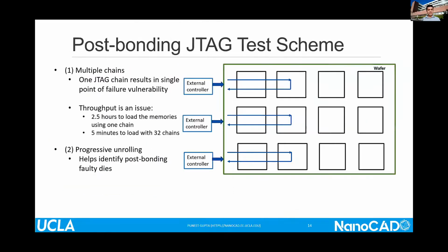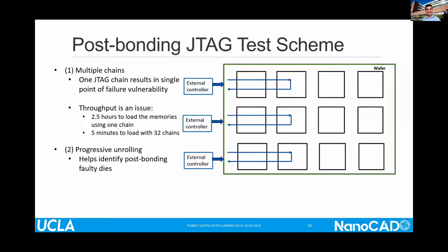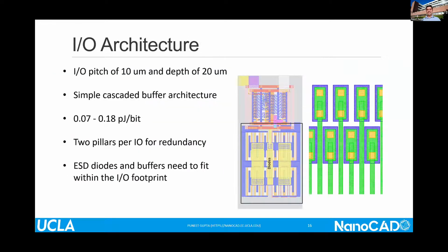So silicon, yes, the cost calculation in the beginning accounts for that, but it assumes that your IOs are of this style. The simpler IOs, these are not SerDes links and things like that. So the IO overhead is there, but it's not massive. There is an overhead of dicing as well, but hopefully not massive.